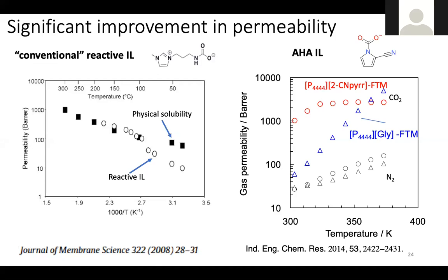One thing related to that might be something the audience could help me out with, because most of my experience with this pertains to teaching process design to senior undergraduates for a few years, and whenever I did a design, I just kind of looked at these things. One of the times I found a sample problem where they were doing separation of azeotropic ethanol using an azeotropic distillation with either pentane or hexane as the entrainer. And so I did the economics on that, or I just looked at the energy cost of running the azeotropic separation after you already were pretty close to the azeotropic concentration.